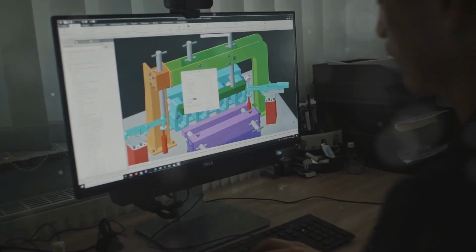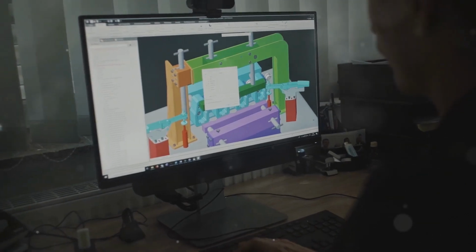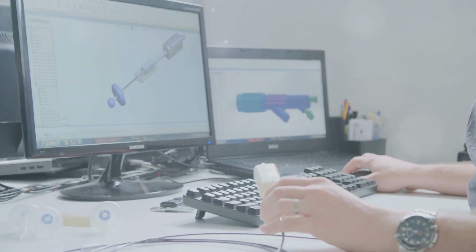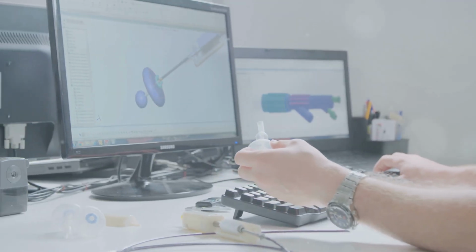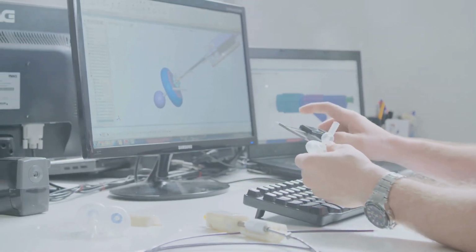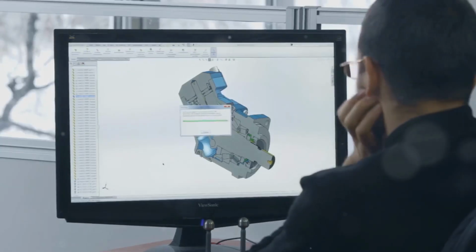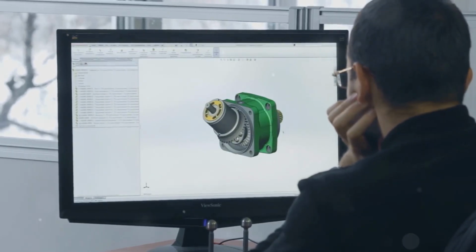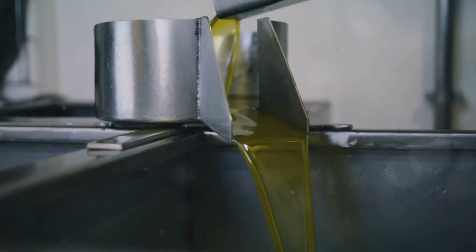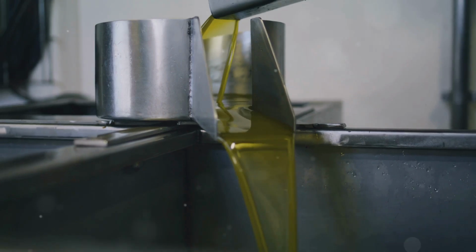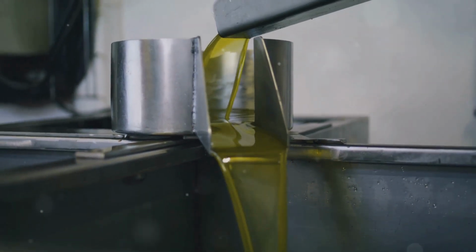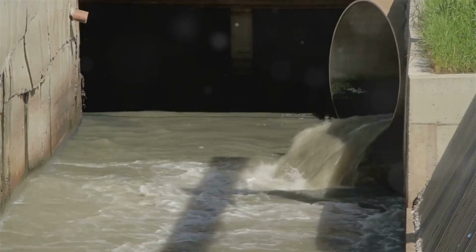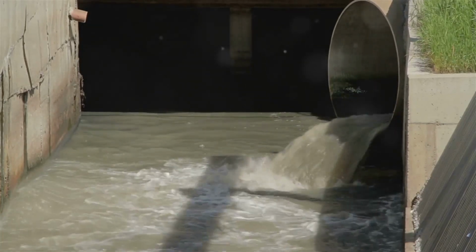A high-quality mesh is crucial for accurate FSI simulations. Then set up the mechanical analysis in ANSYS Mechanical by defining the material properties, boundary conditions, and loads acting on the structure. This setup provides the structural response to the fluid forces. After that, set up the Fluent analysis in ANSYS Fluent by defining the fluid properties, boundary conditions, and initial conditions. This setup characterizes the fluid flow behavior.